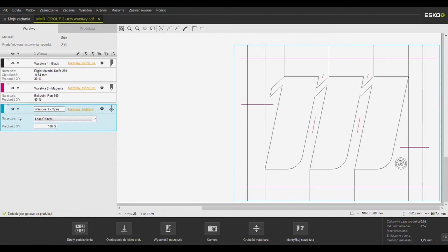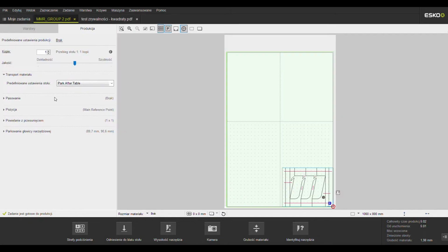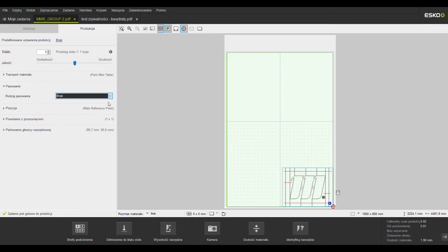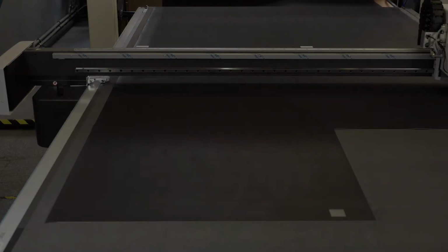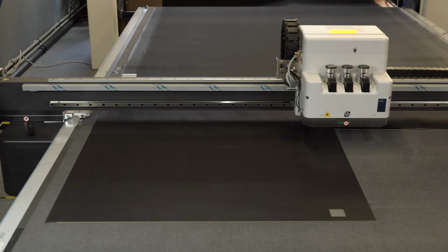The third layer contains the board contour. Having it, the plate shall be cut from the roll. The second rigid material knife tool shall now be selected with the same blade as the first one. Please note that this tool is intended only to cut through plates or blankets. The pre-cut set depth shall depend on the main tool settings. With the use of the laser, point 0 shall be set on the plate. The cutting process shall be activated.